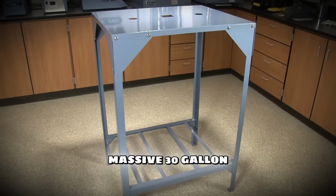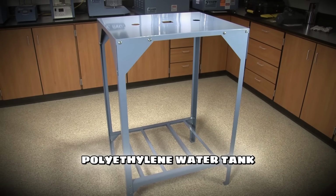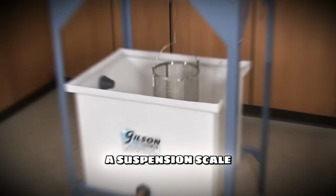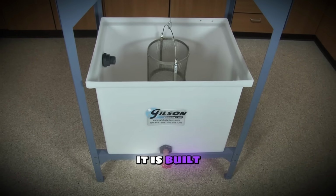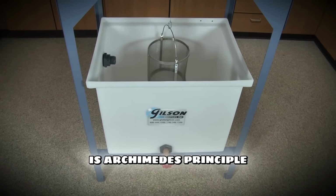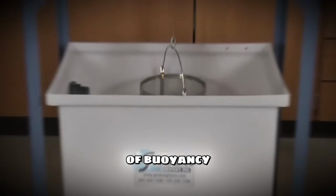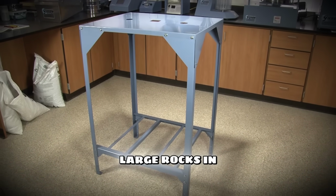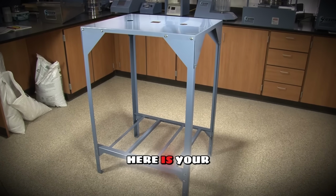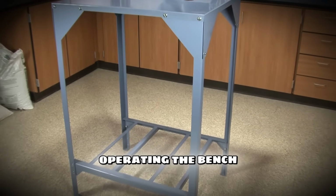It features a massive 30-gallon polyethylene water tank, a heavy-duty steel bench, and usually includes a suspension scale and a wire basket. It is built to handle the heavy lifting. The principle here is Archimedes' principle of buoyancy. We are going to weigh the large rocks in the air and then weigh them while they are completely underwater. Here is your simple explanation for operating the bench.